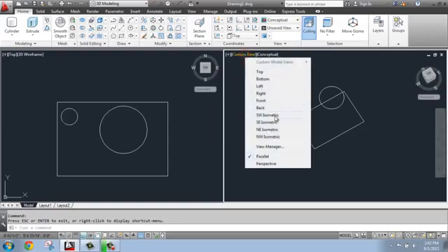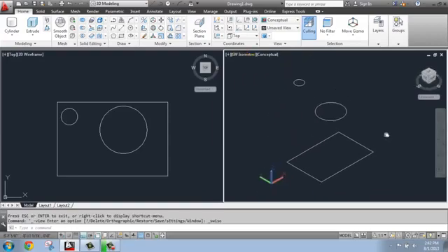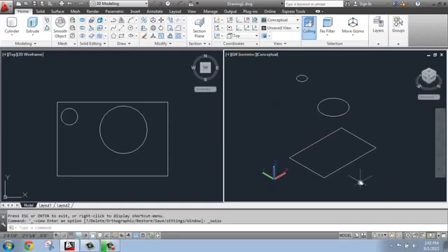Just switch that back to my isometric view. I really recommend that, as you're working, unless you really have to be in a custom view for some reason, it tends to be best to keep it in an isometric view. You have a better idea of where you're at in the AutoCAD universe, if you will. Once we have some cross sections created and they're going either up or down in space the way that we like, and I could be scooting these around, but I want to keep it fairly simple.